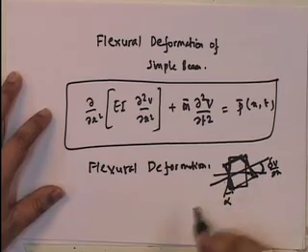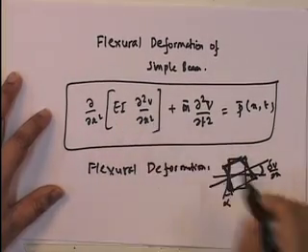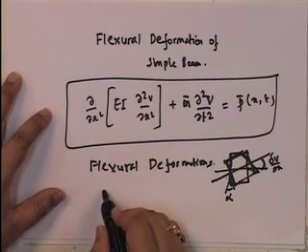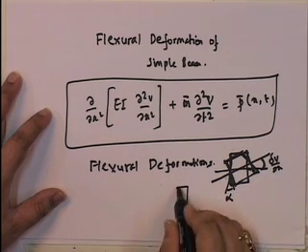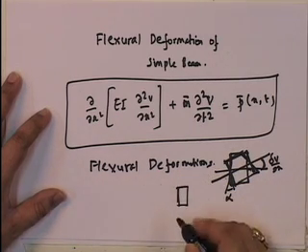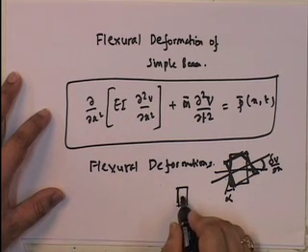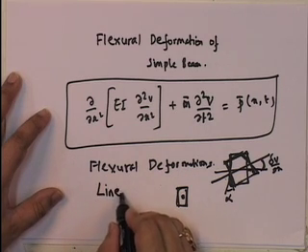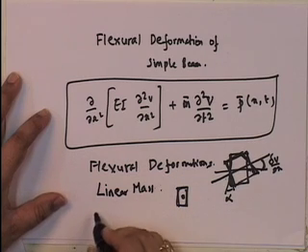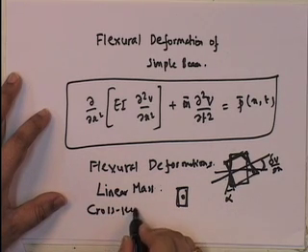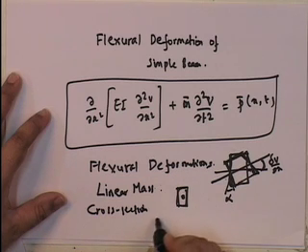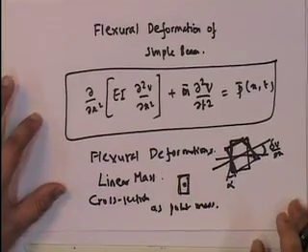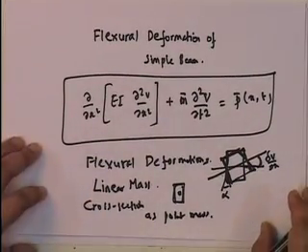Okay, and that is the reason why we could say that the curvature is directly this. So, it is only flexural deformations, and also we only took the fact that the beam was not deep enough, so the beam was like a point mass, so that it only had cross section as a point mass. These are the assumptions that we made in deriving this.